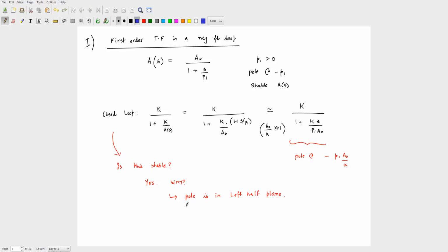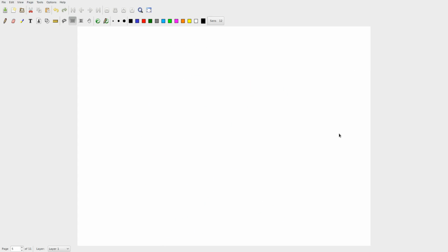Okay, all right. With this picture in mind, let's go back to what we had, which was our transfer function, which is of this form, right? Let's go and plot this and see what we can get out of this. So this transfer function is your closed loop transfer function, and the transfer function is basically V out by V in is this quantity. Okay, I am just going to massage this a little bit. I will write this as S divided by A naught P1 by K. Okay, and I will remove this K from the numerator. Okay, and we had the open loop transfer function itself.